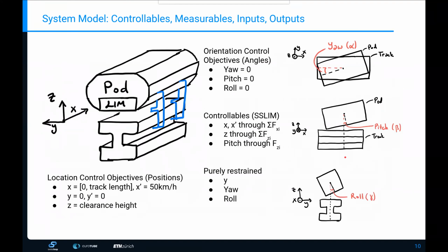Well, the actual challenge, if we were to do it in a controlled manner, would be to control the Y deviation, because there's not a lot of playroom in there, and it's by itself unstable, because if the limb has a positive roll angle, for example, then the fields will actually repel each other away from the I-beam, so the limb will want to fall over. So if we could find a way to control it, this would be the hardest one.